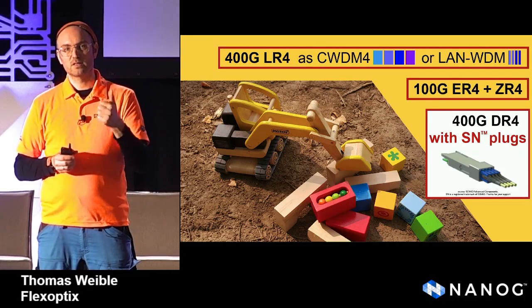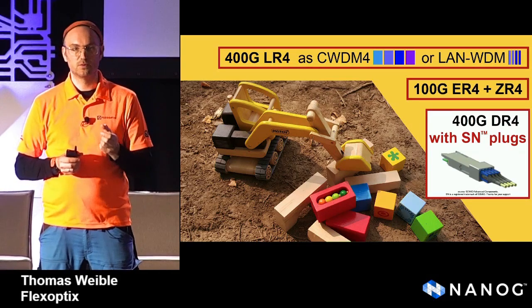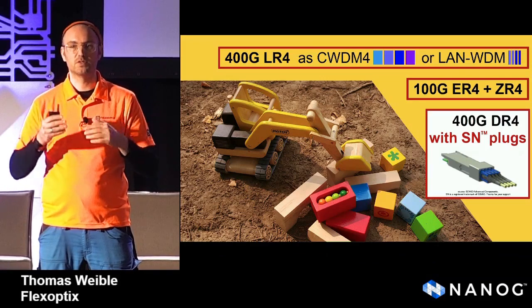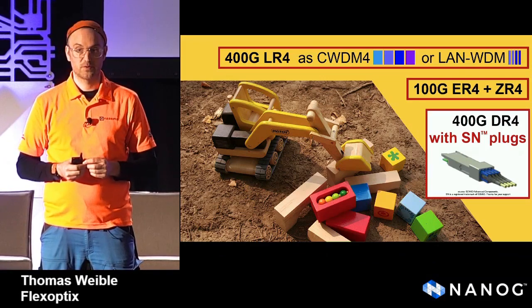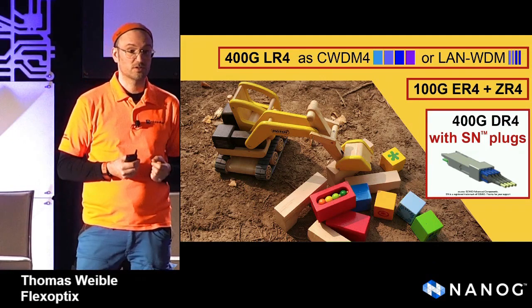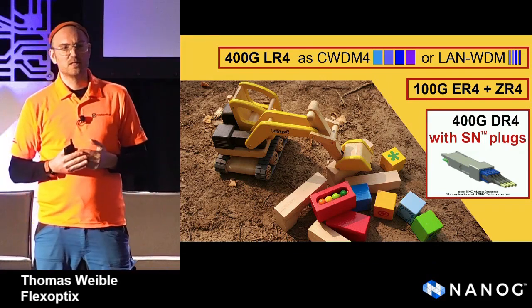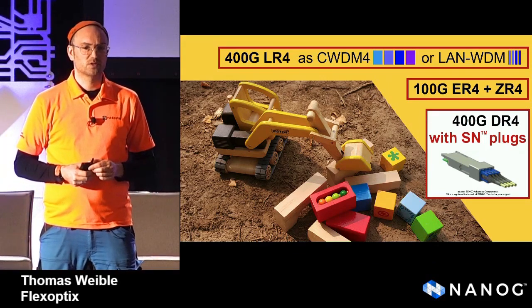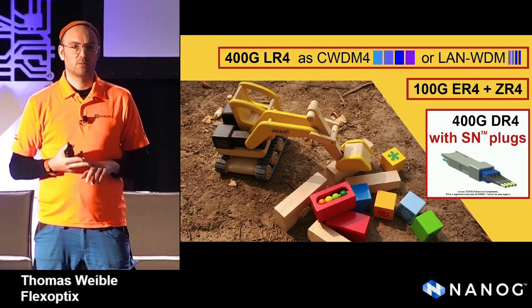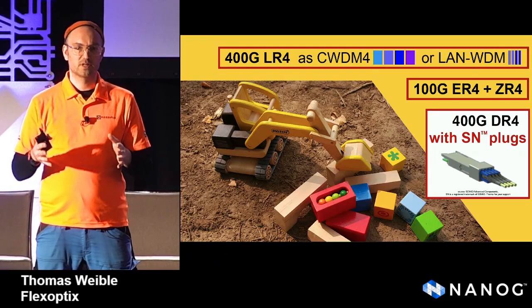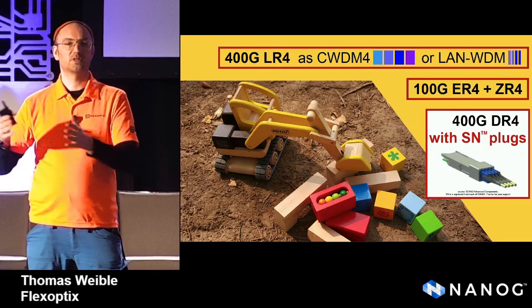And if you want to maintain a single link, you can just release two ferrules, and the other 6 ferrules will stay in the transceiver. Why is this so important, or why is it so interesting? With 400 gigabit, it's not only a pure 400 gigabit transceiver. You can also imagine applications doing, out of a 400 gigabit transceiver, driving 4 times 100 gigabit.